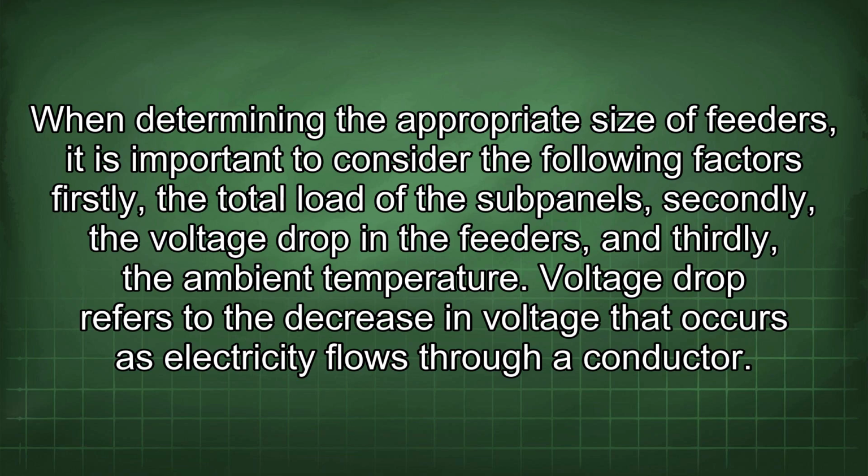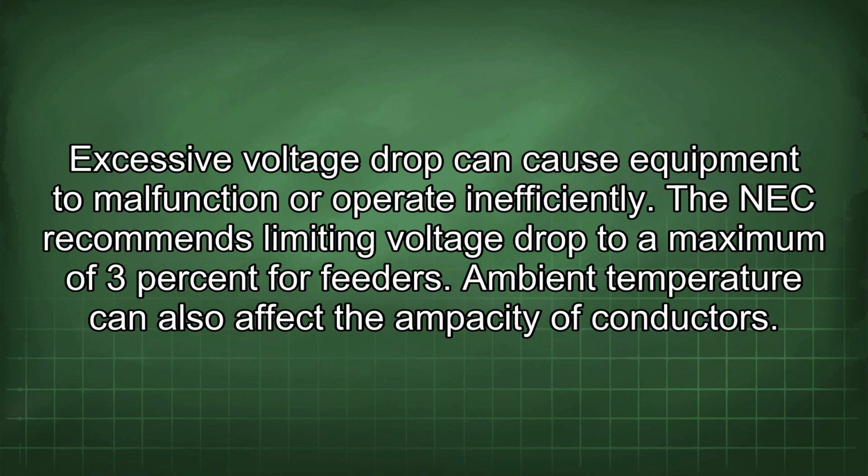Voltage drop refers to the decrease in voltage that occurs as electricity flows through a conductor. Excessive voltage drop can cause equipment to malfunction or operate inefficiently. The NEC recommends limiting voltage drop to a maximum of 3% for feeders.